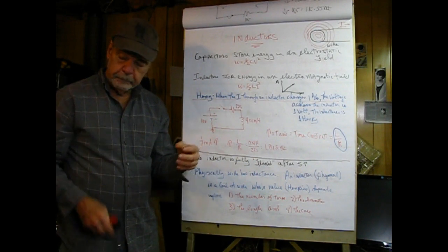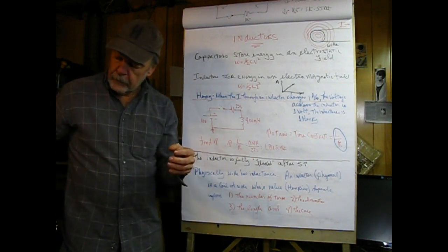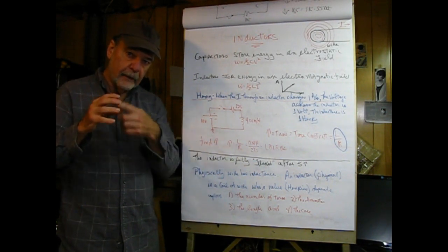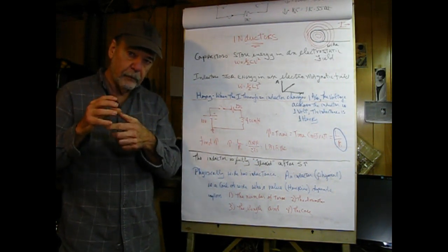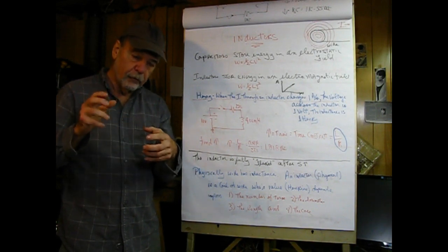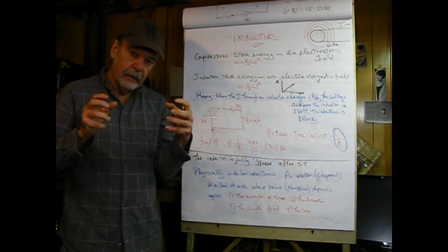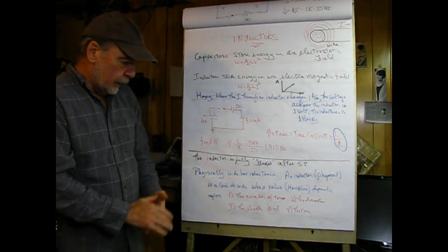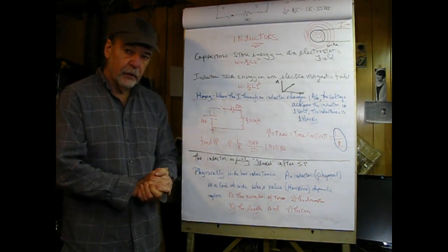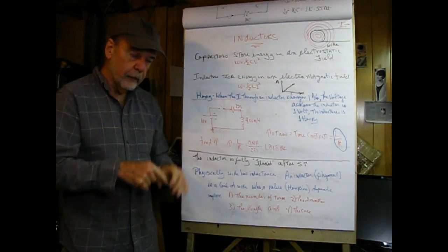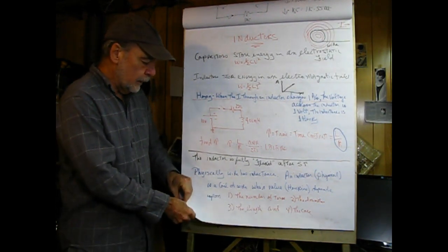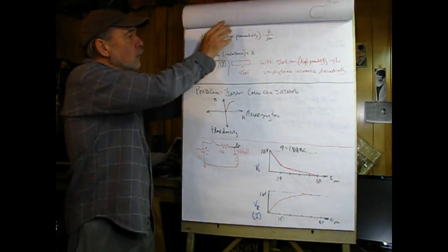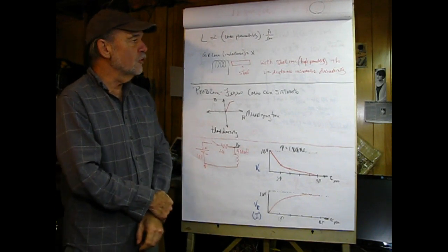When you think about it, if you have a long inductor, the magnetic field formed by the wires at this side would not interact and support the magnetic lines formed by the wires at the other side. So you don't get that additive effect as if you had a short inductance. And fourth is the core, and that's the material inside the coil of wires. And we'll look at that now.